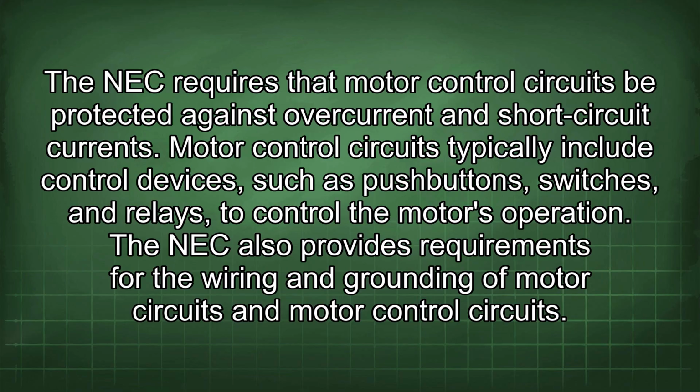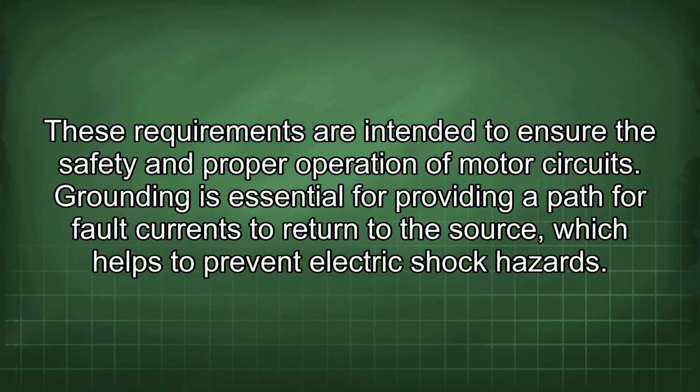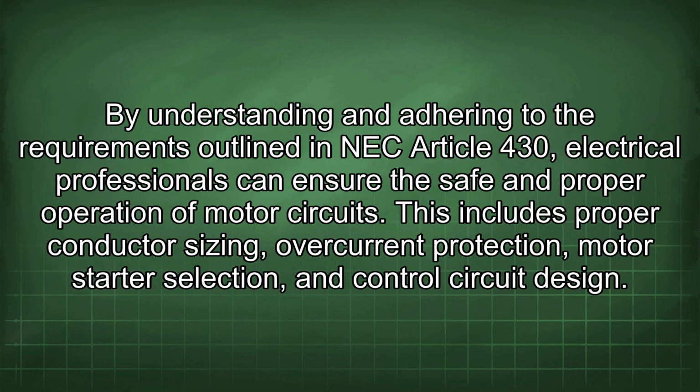The NEC also provides requirements for the wiring and grounding of motor circuits and motor control circuits. These requirements are intended to ensure the safety and proper operation of motor circuits. Grounding is essential for providing a path for fault currents to return to the source, which helps to prevent electric shock hazards. By understanding and adhering to the requirements outlined in NEC Article 430, electrical professionals can ensure the safe and proper operation of motor circuits.